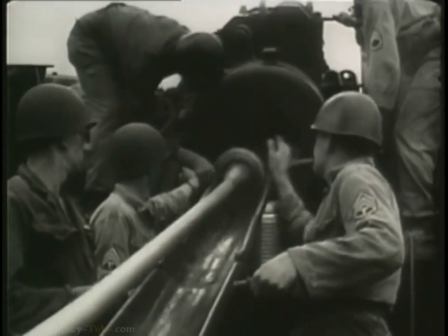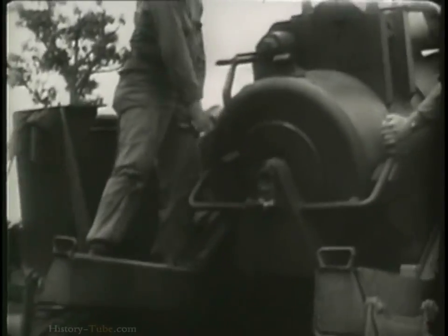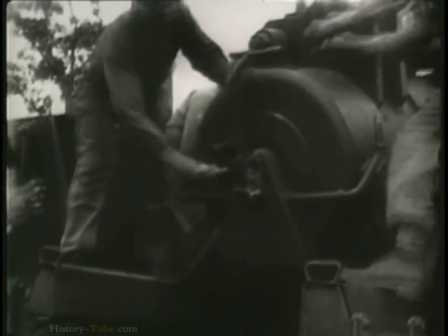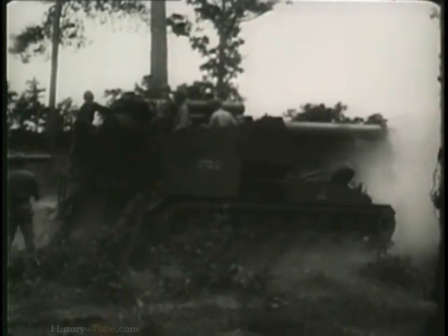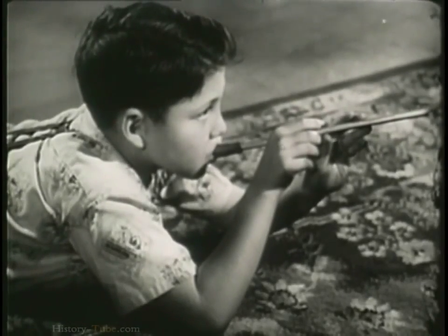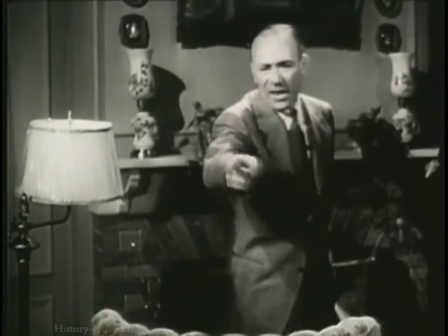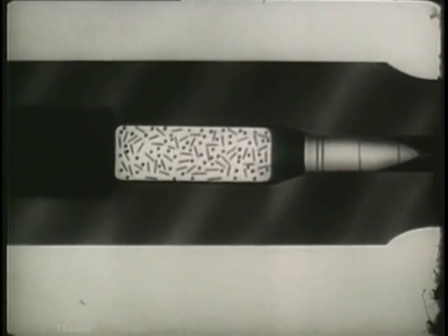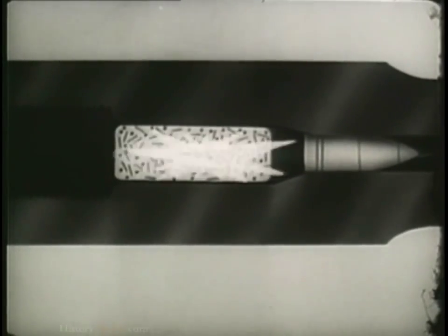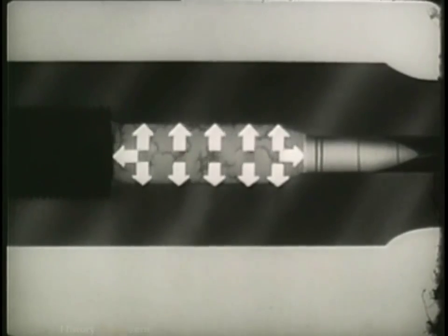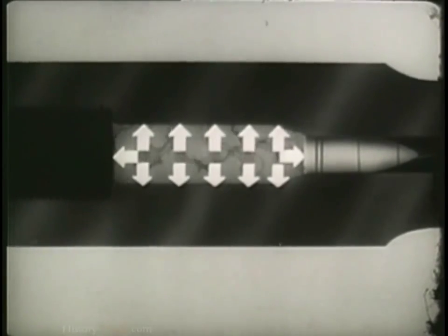Let's look first at the problems involved in launching our ammunition with launching devices that are complex, precision-made instruments, but which operate on a principle as simple as that employed in a pea shooter. When the pressure behind the projectile becomes strong enough, the projectile will move. In any gun, howitzer, mortar, or small arms weapon, the pressure behind the projectile is caused by the burning of the propelling charge or propellant, which forms a tremendous amount of gas in the chamber. This pressure is measured in thousands of pounds per square inch and is exerted equally on all surrounding surfaces, but with different results.